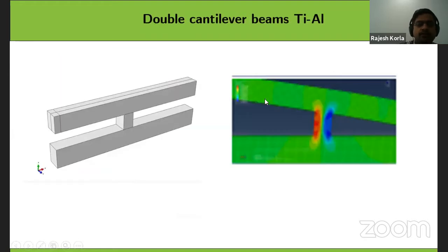And further, what we want to do is calculate back stress. For example, what is the effect of cyclic loading? Producing a cyclic loading in micro tensiles and micromechanical testing is very difficult. So we came up with our own geometry. It's called seesaw geometry. For example, apply load like this. Basically, this is how the beam looks. Apply load like that.